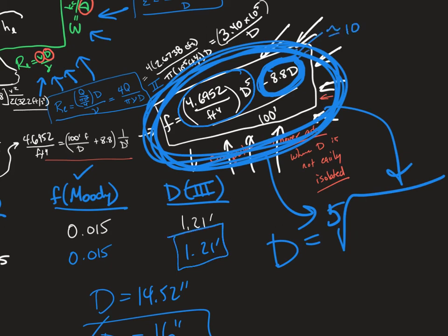And if I plug in 1.21 right here, well, let's see real quick, 1.21 to the 5th, I think they're going to be pretty close to the same order of magnitude. And yeah, same order of magnitude. So this one's 12.2. So yeah, we were not going to be able to ignore it on this particular problem. So sometimes you can, especially if the pipe is long enough and there aren't that many fittings, then you know that the friction losses are going to be important. If it's a short pipe with more fittings, well then, so.